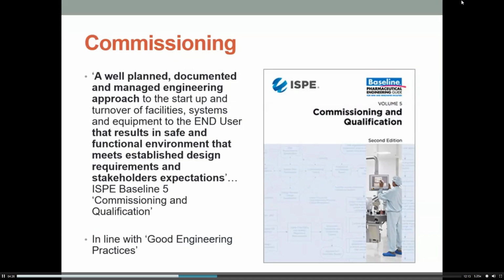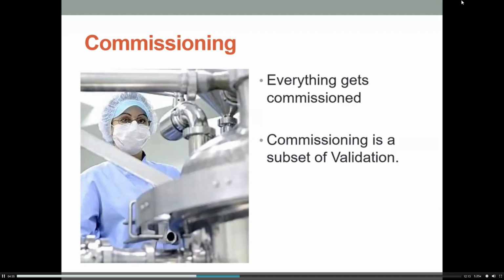Commissioning is a well-planned, documented and managed engineering approach to the startup and turnover of facilities, systems and equipment to the end user that results in a safe and functioning environment that meets established design requirements and stakeholders' expectations, and that comes from the ISPE Baseline 5 Commissioning and Qualification. So it's worth having a look through that document. It's got a lot of good information in it, and that is in line with the good engineering practices. So everything gets commissioned, and commissioning is a subset of validation. It's the studies we do to see how things are working and to make sure everything is working correctly.